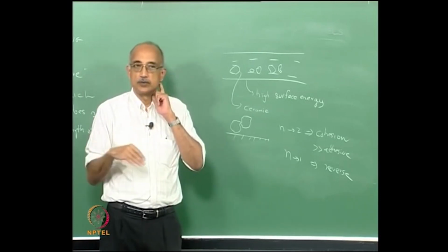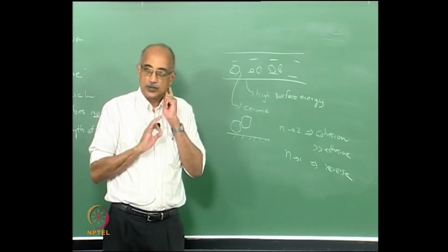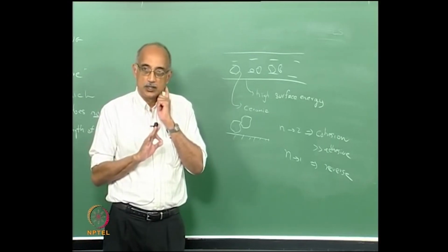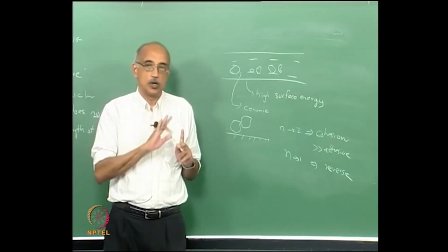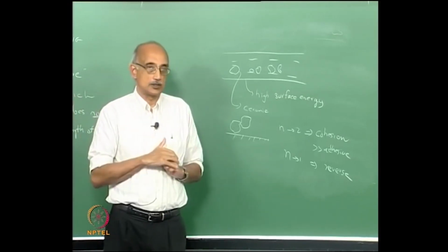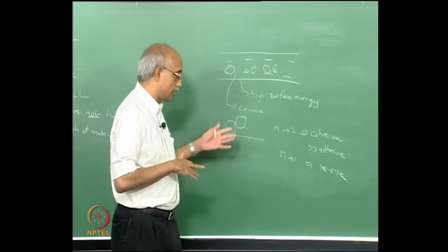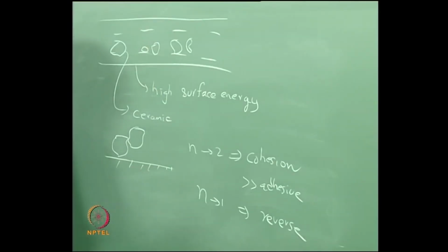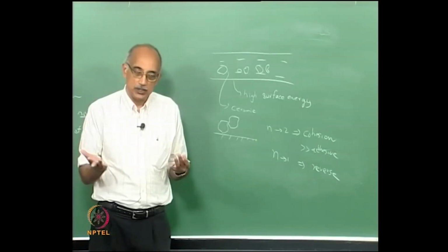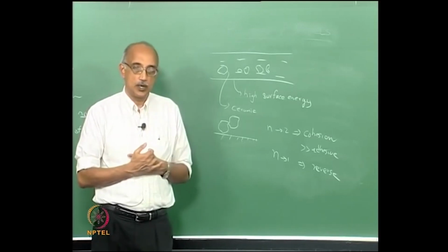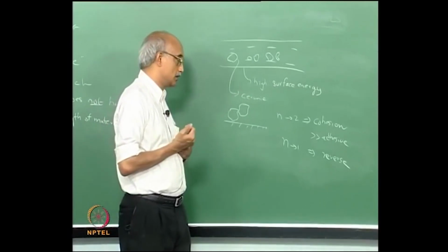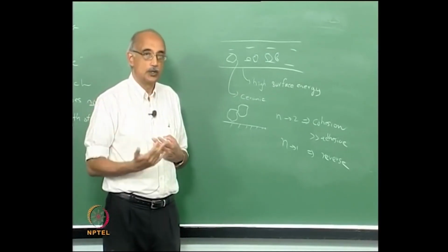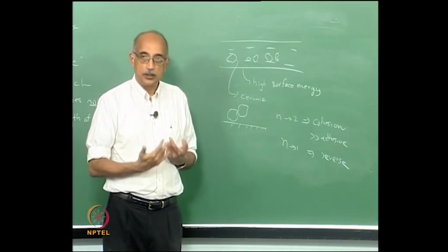So, it is actually a trade off. There is usually an optimum cohesiveness index at which you get good flowability, but at the same time minimum loss of material to contacting surfaces. In fact, it can be stated as an optimization problem, and people have done that. You can basically predict for various materials, for various applications, what is an optimum cohesiveness index to achieve what you are looking for, high throughput, but at the same time good quality.